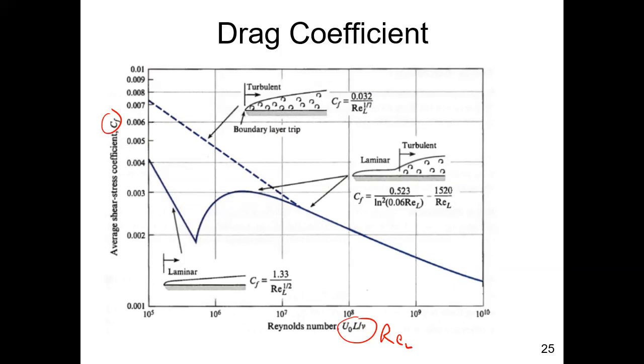And this is figure 9-10 in your textbook. In this particular example, we have a boundary Reynolds number at the trailing edge of 7.63 times 10 to the 6th. Go up to your curve, go over, and you read out 0.0029. We calculated 0.00288. So this is a nice little check on what we just did.